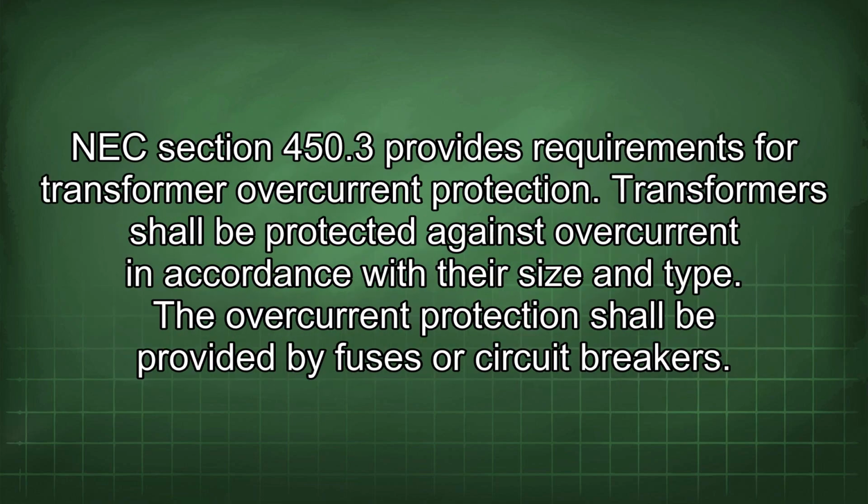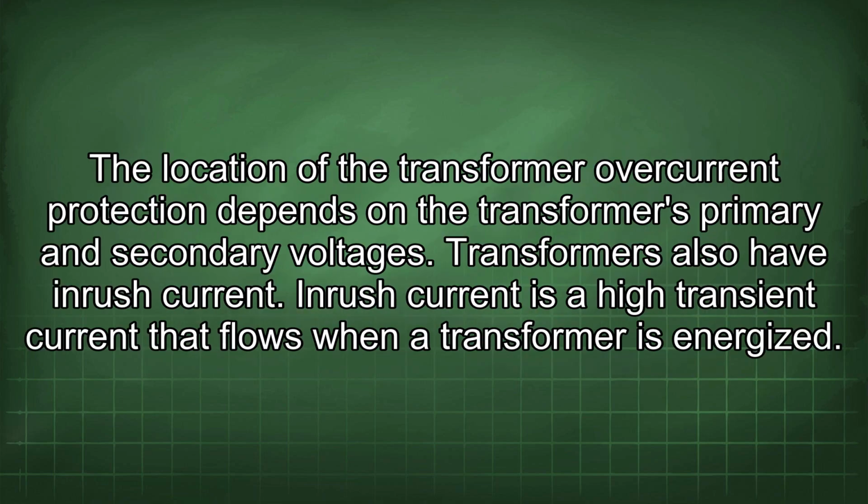NEC Section 450.3 provides requirements for transformer overcurrent protection. Transformers shall be protected against overcurrent in accordance with their size and type. The overcurrent protection shall be provided by fuses or circuit breakers. The location of the transformer overcurrent protection depends on the transformer's primary and secondary voltages.